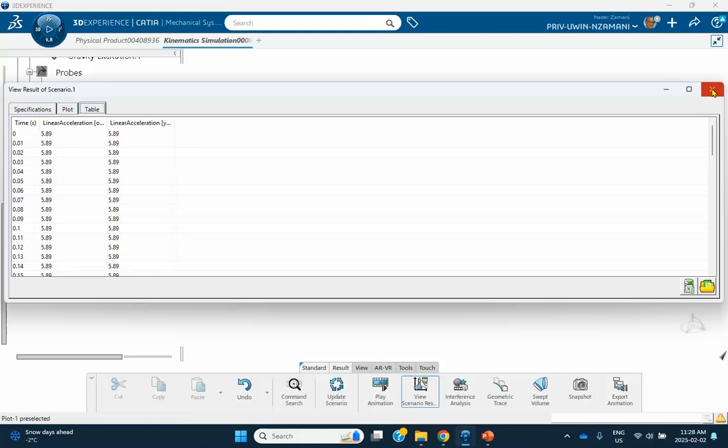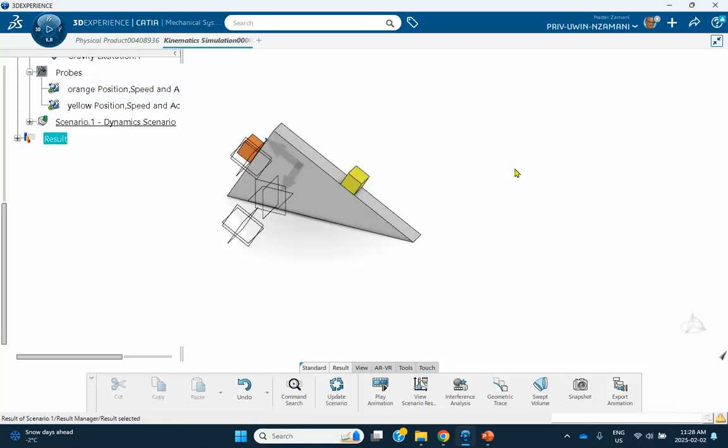The reason it makes absolutely no difference is that if you go back to tutorial 24, you see that even when there is no cable, when there is a prismatic joint, even though you may define a coefficient of friction between the two pieces, if you have a prismatic joint, it'll totally ignore that value of the coefficient of friction. So the cable joint in the way we're using it here is totally useless because you cannot incorporate friction.